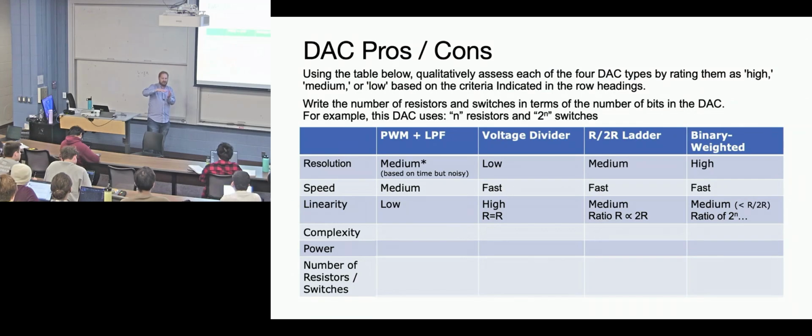There's process variation, and there's a polishing step which can literally round off the corners of your resistors, reducing some of their resistance. There are all these things that give you variation. So they make structures that try to guarantee that two resistors would be the same value if they're exactly the same size. That's why here I'm going to say all the resistors are the same size, so the likelihood that there's going to be variation between them is low.